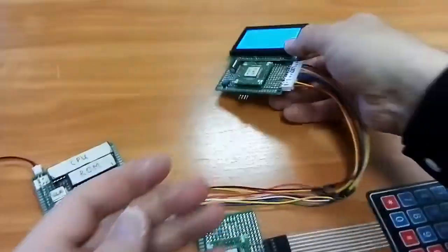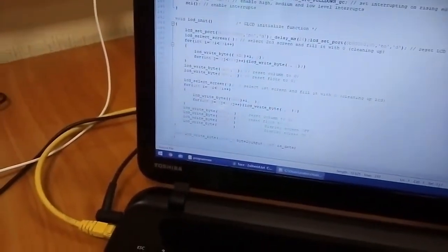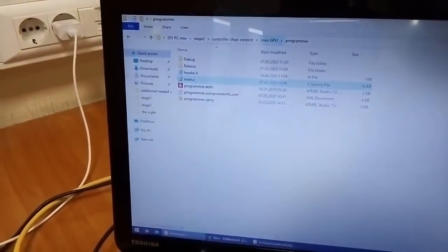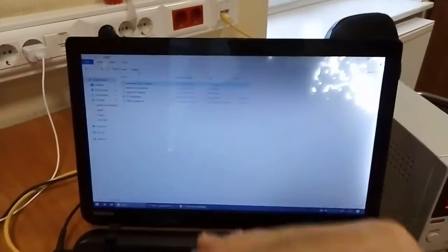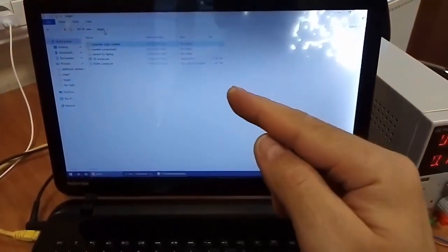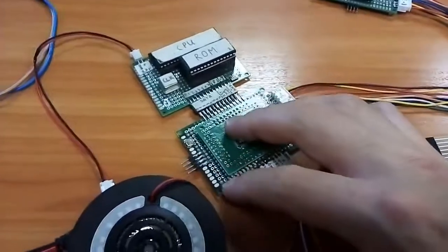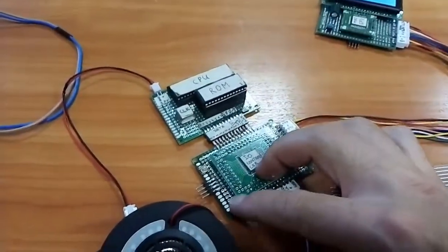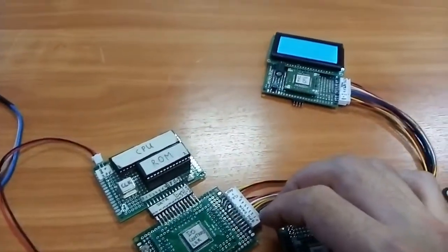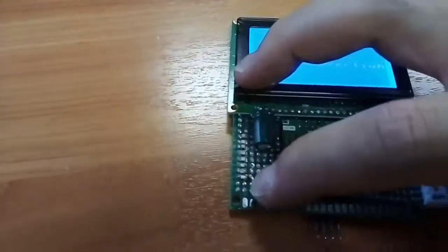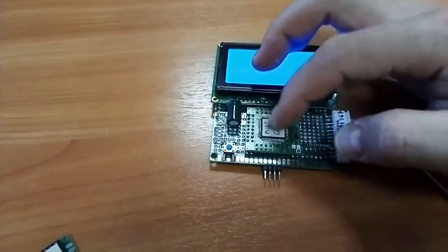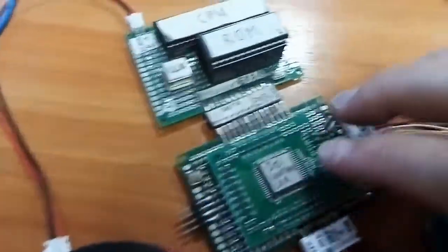As a rule, my suggestion is, if possible, all the time use light emitting diodes for diagnostic purposes. If something goes wrong, something doesn't work at all, then you can change your code. Your code consists of steps, and after each step you can redirect the output to the light emitting diodes to find out what output of this step is present. So you can pinpoint the problem by searching step by step through all the program.